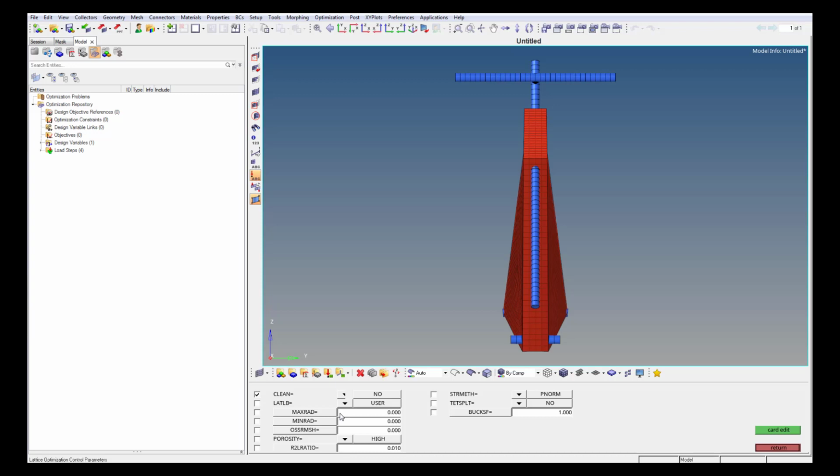LetLB can be used to verify or automatically set the lower bound value. This process aims at generating a model that allows for maximum beam element removal and at the same time retaining reasonable model compliance performance. Porosity defined as low will lead to a final design with mostly fully dense material distribution, and is appropriate if compliance minimization for a given target volume is required. The amount of intermediate densities in a model depends primarily on the penalty applied. This is similar to the penalty applied during a topology optimization.